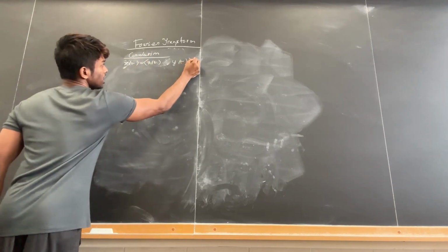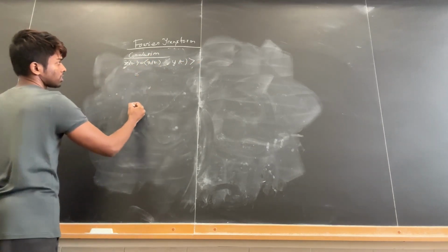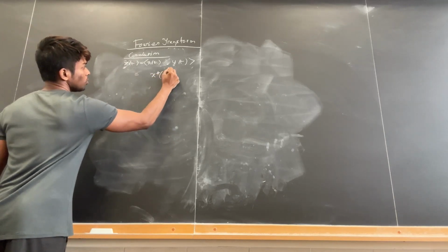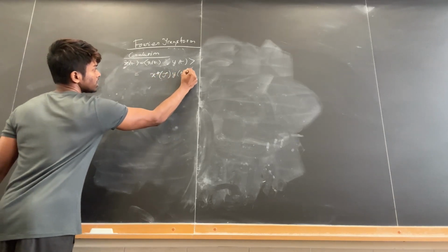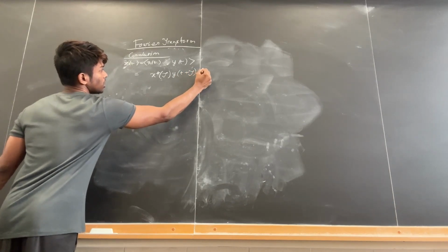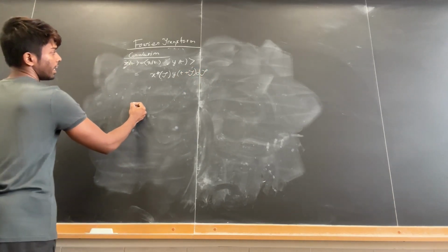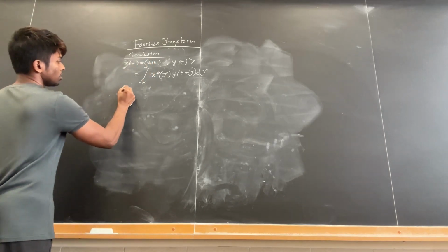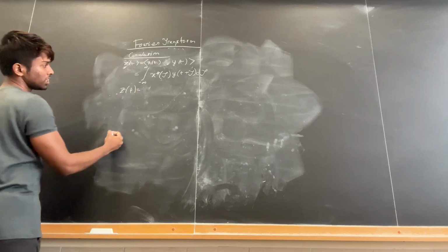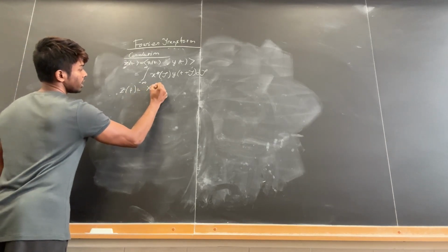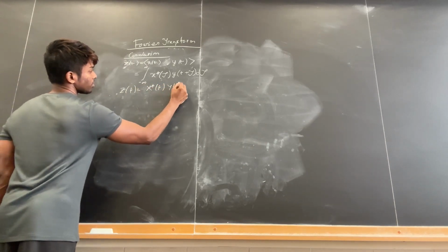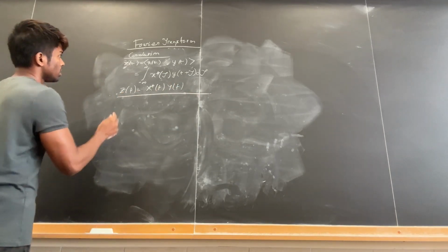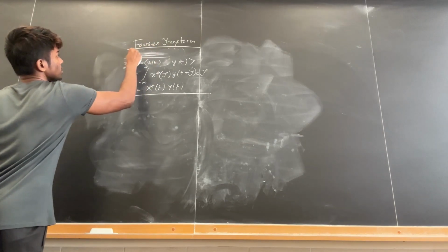It is some sort of inner product, and it can be expressed as z(t) equal to the integration from minus infinity to plus infinity of x conjugate(tau) y(t plus tau) d tau. And in the frequency domain, this is just X conjugate(f) times Y(f). That is the correlation property.